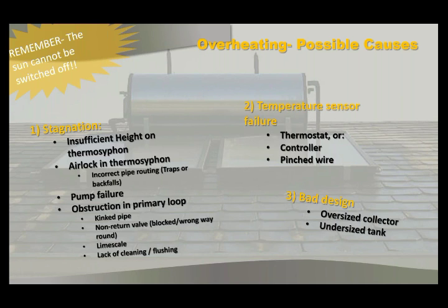Temperature sensor failure. This would be primarily on a pumped system, so your pump would not be told to switch on, and it can be as simple as an alarm guy installing an alarm and standing on a sensor wire and severing it. I mean, you could install a perfect system today, and next week you've got a catastrophe on your hands because the sensor wire wasn't properly routed.